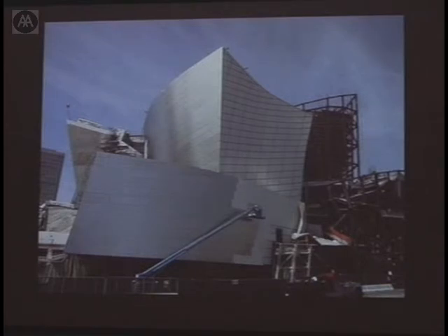You have to know that there is a tolerance jump. You have to work that tolerance jump into the detailing, to have variable geometry details that you can survey with lasers to actually register them to the kind of tolerance you want in the final skin on the outside. So that becomes part of the design in the shop drawings, but that decision isn't made by the computer, it's actually made by you.